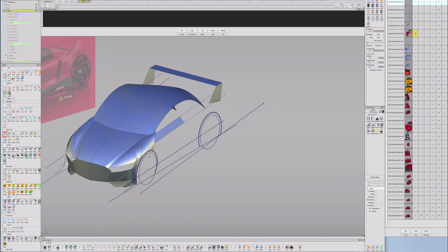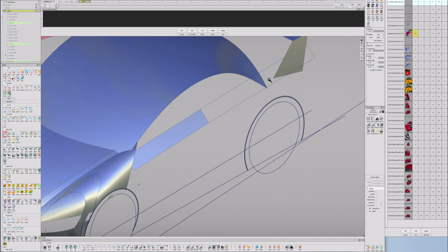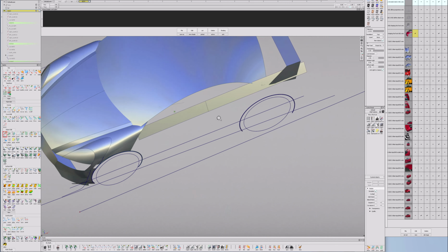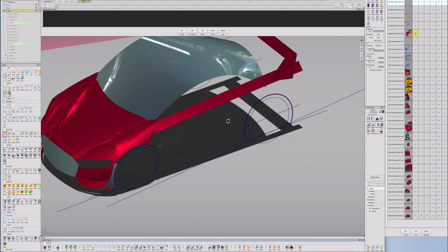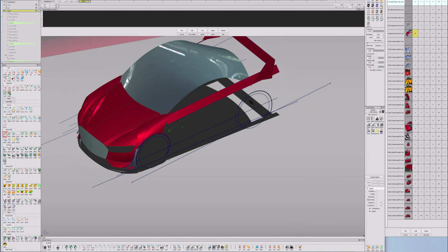And sometimes it's really annoying because the cut piece can be big and you can be really zoomed in and not notice it and select something wrong, etc. In shaded mode it never happens. If you split something, it's always shaded. So this is a really convenient way to work.